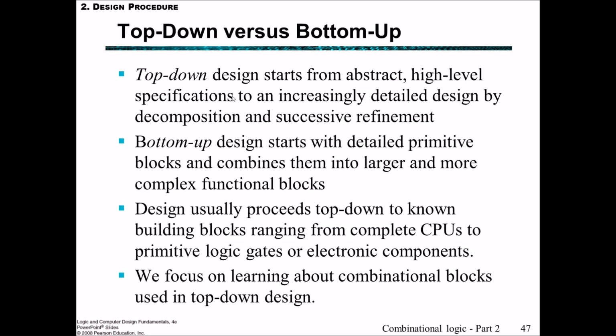In terms of the design procedure, the two most common ways to think about it are top-down design and bottom-up design. Now, in this subject, we're going to be focusing on top-down design. Top-down design starts from the abstract, high-level specification and becomes increasingly detailed as we decompose and successively refine our design. Whilst bottom-up design starts with very detailed primitive blocks and combines them into larger and more complex functional blocks. In general, the design process that we would advocate would usually proceed from top down to the known building blocks, ranging from complete CPUs all the way down to primitive logic gates or electronic components.